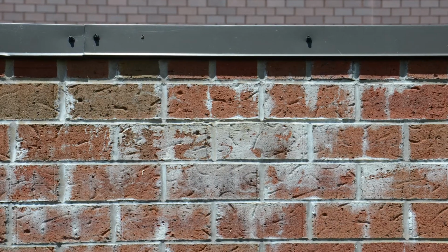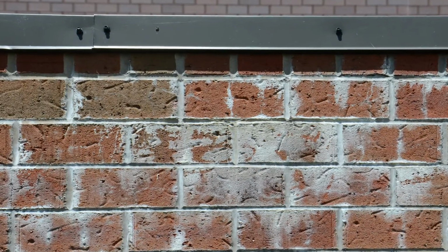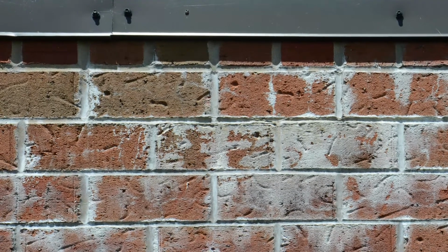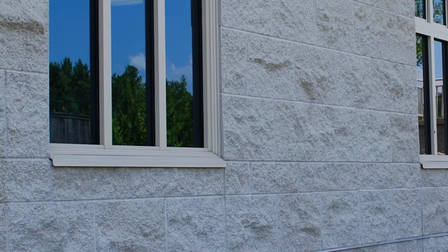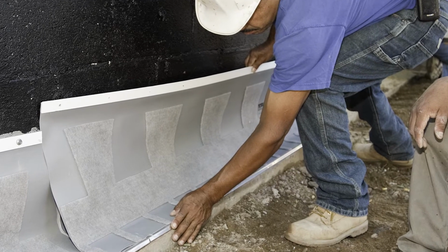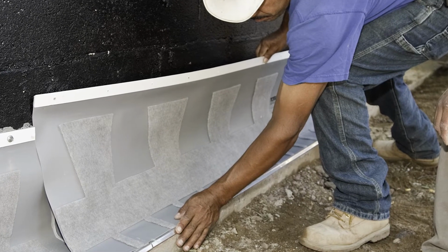Moisture that is not removed from the wall systems will form efflorescence or discoloration in unsightly walls, and likely create callback situations for your contractor to address the disappointing results. Knowing that, trained masons understand that the identification of areas that need flashing and the proper installation of masonry flashing will ensure they are doing the best possible job they can.